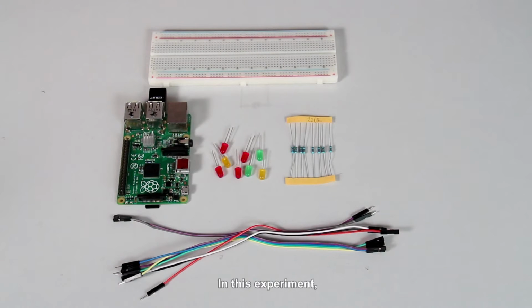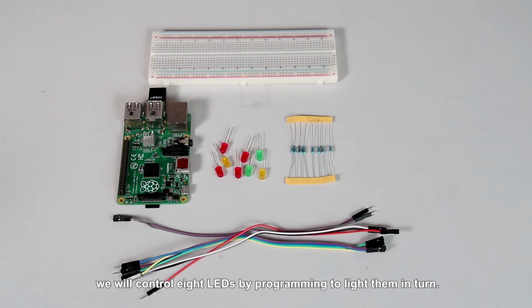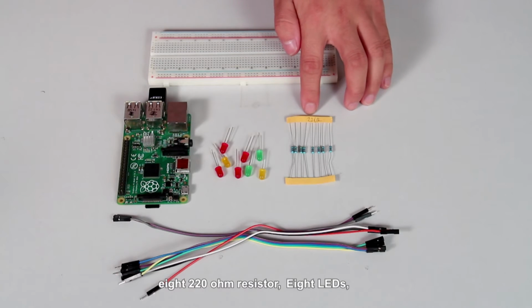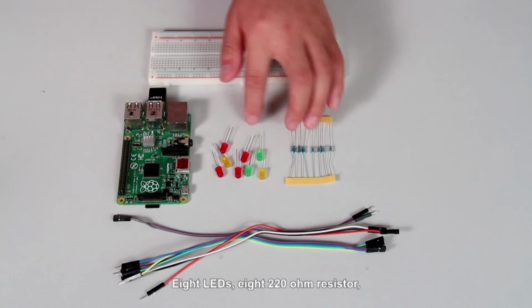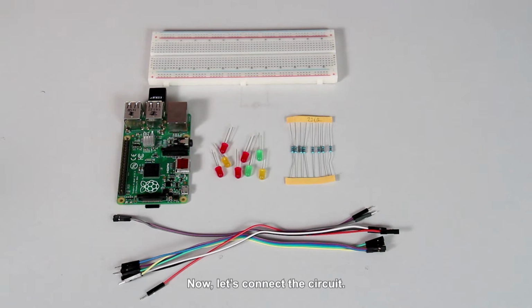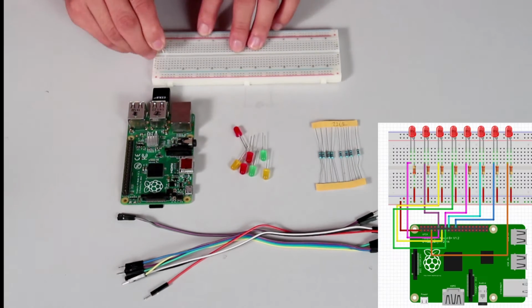In this experiment, we will control 8 LEDs by programming to light them in turn. We need the following components: 8 220 ohm resistors, 8 LEDs, 2 bond wires, and a breadboard.